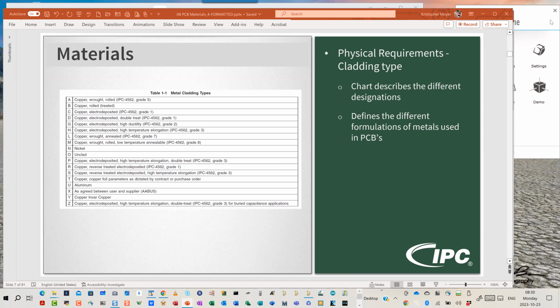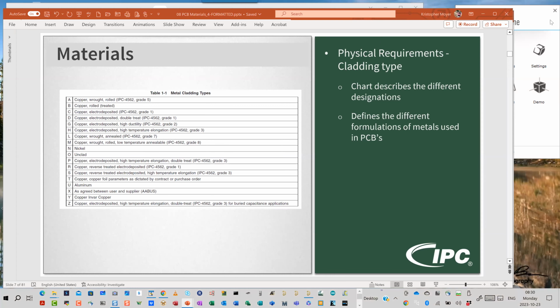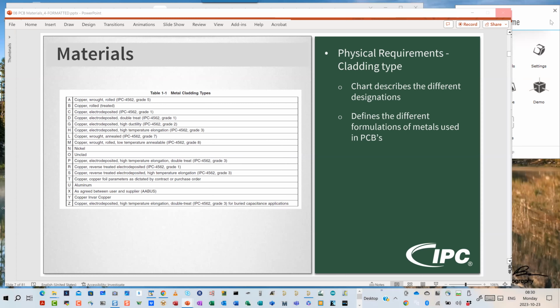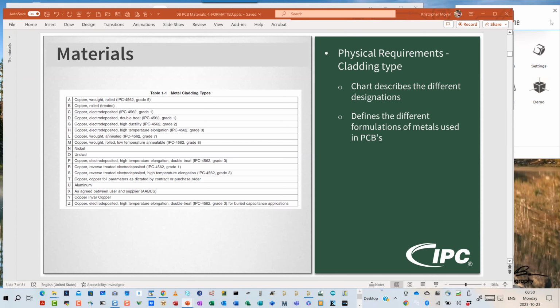Yes, annealing is the process by which we take a metal, raise its temperature to a temperature greater than 1/2 of its melting temperature, and hold it at that temperature for some duration of time sufficient to allow the crystalline grain structure to relax and spread out. Annealed metals therefore soften and become very malleable or pliable or flexible. These are very good at tensile loads, bending loads, where they can bend and stretch without breaking.